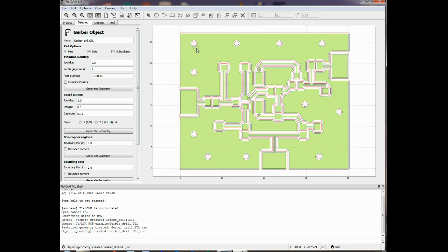I just want a hole straight through the copper, straight through the fiberglass, straight through the copper on the other side with no relief, because I want to drop a Vero pin through and connect the two together, which would normally be the job of a via. So if you were having this commercially made, you drop vias in, not holes. The vias would then connect. They'd be through hole plated from the top to the bottom, but I'm going to drop a Vero pin through, so that's where the confusion's crept in.